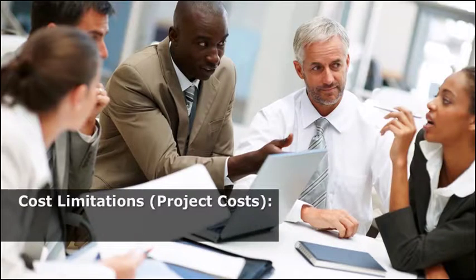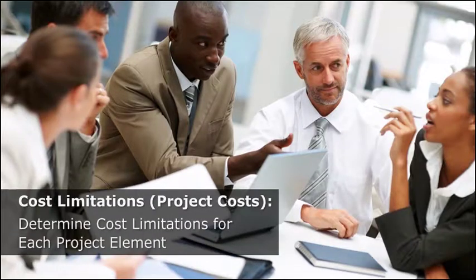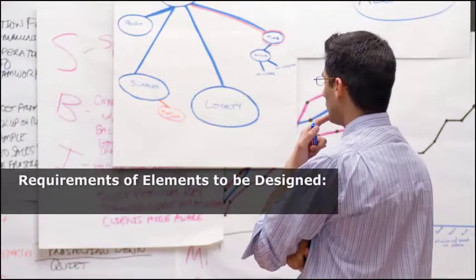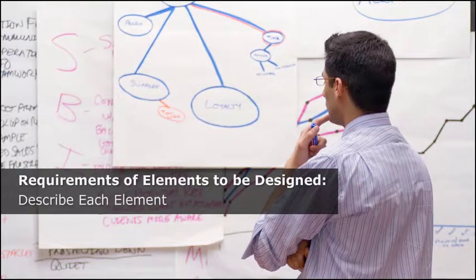2. Cost limitations, project costs. Set total project limitations and determine cost limitations for each project element, such as civil, structural, etc. 3. Requirements of elements to be designed. Define all elements to be designed. Identify any constraints on any of the elements. Identify requirements of elements to be designed. Describe each element, giving design loads, functions, flows, lengths, clearances, etc.